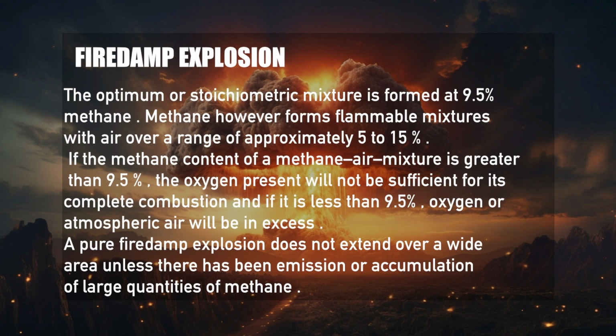If the methane content of a methane-air mixture is greater than 9.5%, the oxygen is not sufficient for complete combustion, and if it is less than 9.5%, oxygen will be in excess. A pure fire damp explosion does not extend over a wide area unless there has been emission or accumulation of a large quantity of methane.